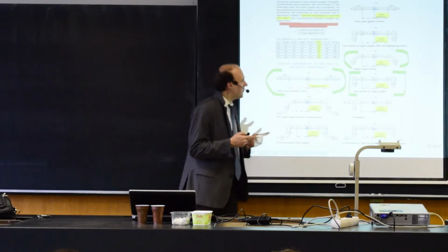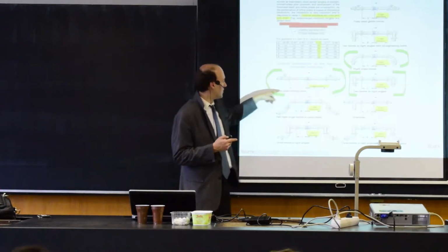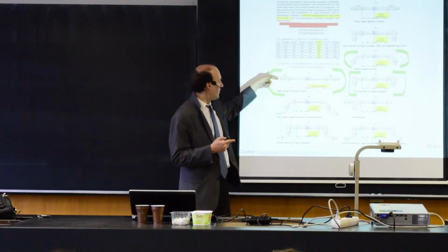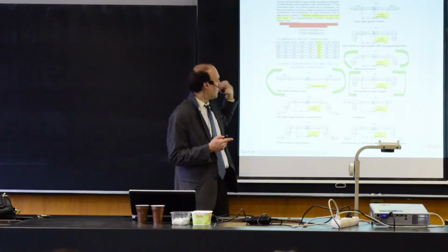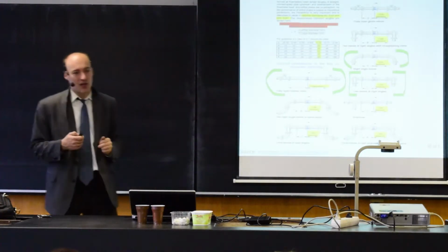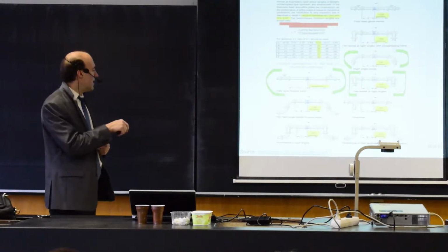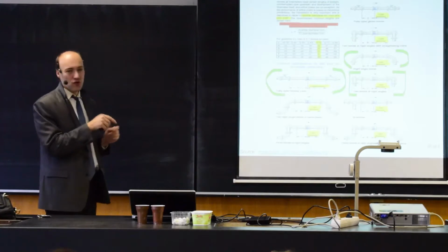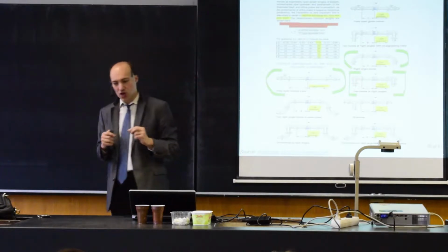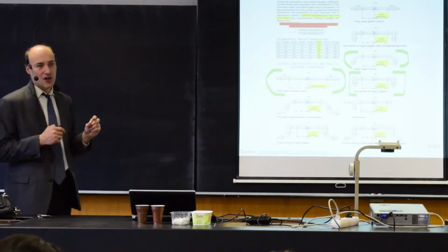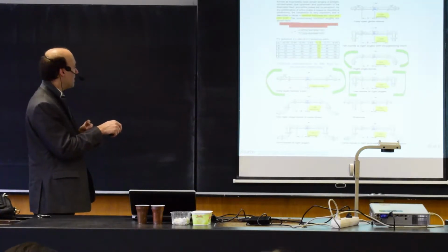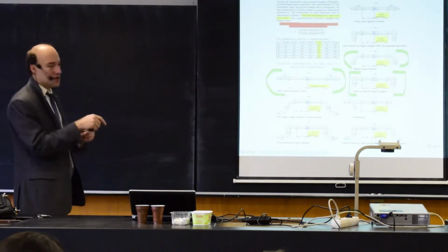It differs for different arrangements, so let's take a look first at this. Here you have the orifice plate. Here you have a fully open valve in front of it. Behind the orifice plate, it's not that critical. You just need to keep at least 5 pipe diameters. But in front of the orifice plate, you need to keep a long distance. And this distance also changes with the ratio of the pipe diameter to the orifice plate diameter, which is typically named beta here. You see it's a ratio.